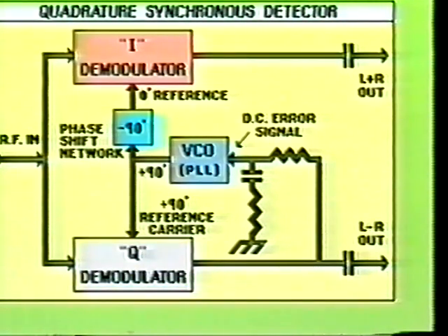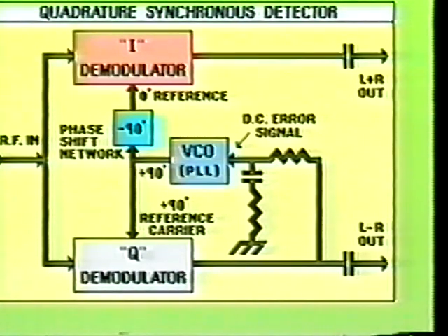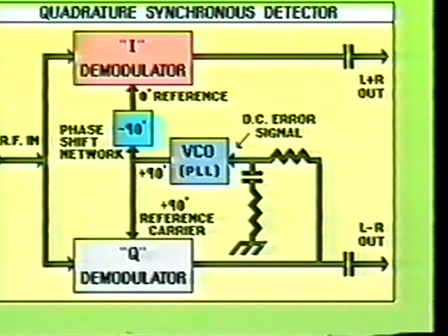The system just described would be excellent for AM stereo, except that the envelope detector in the monaural AM receivers already in use can't see the I or Q sidebands. They can only see the vectored sum of the two. Therefore, the standard envelope detector is not capable of seeing the phase-shifted information. It can only see the RMS total of the amplitude modulation and carrier, regardless of phase.